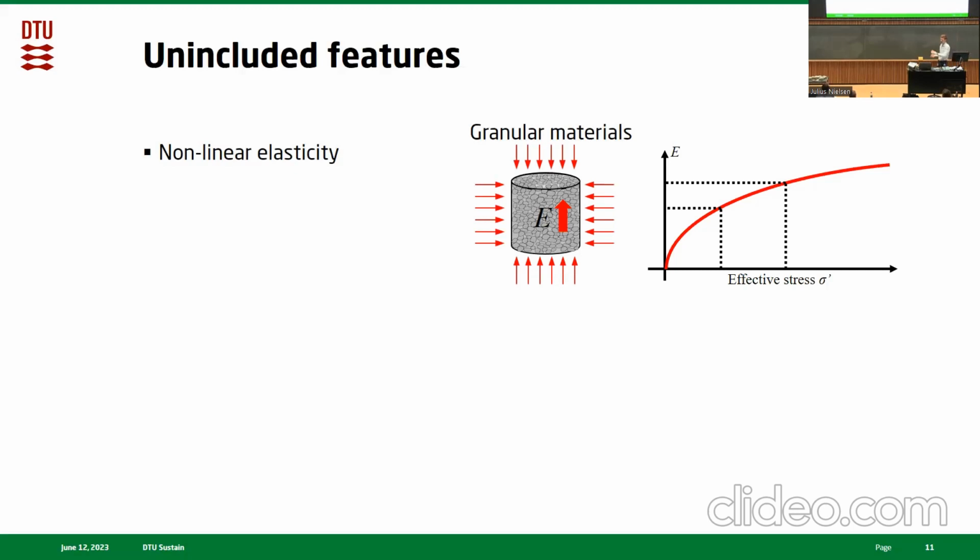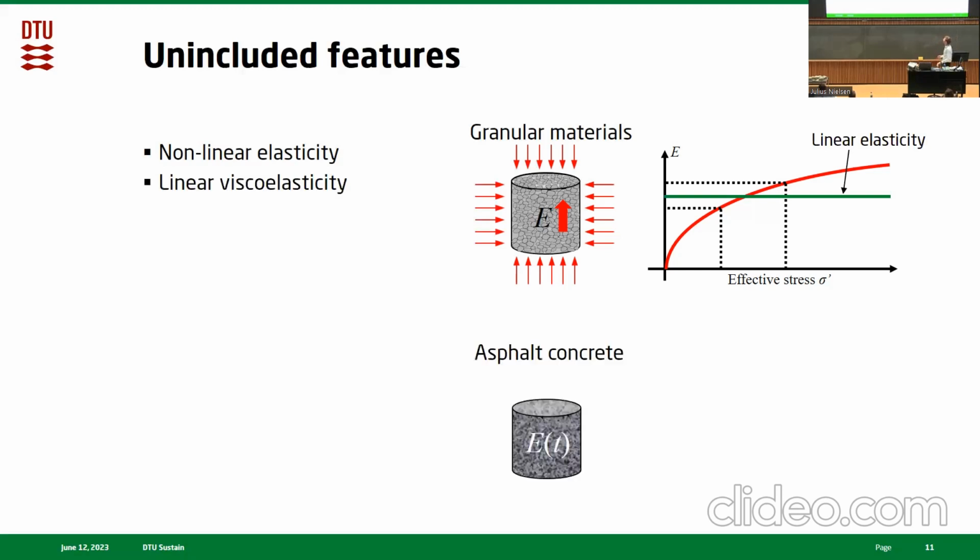And as I said, with linear elastic theory, all layers have to be the same in all directions. So we cannot introduce a local increase in modulus. So this is super difficult to actually apply in our layered elastic system. What we can do is assume some average linear elastic modulus for these layers.